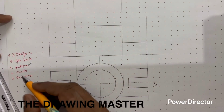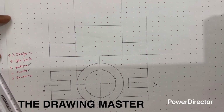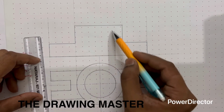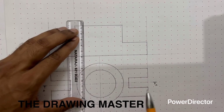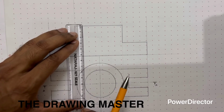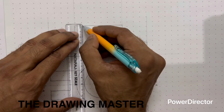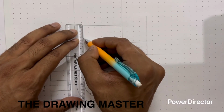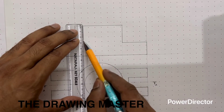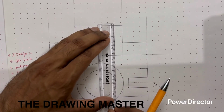Now after making the outline, second we have to draw the cavity. We have to find out the cavity. So in this whole section at the center, here is the cavity, means this circular hole. So let's take the projection from the circular hole. And this cavity means this hole is of depth 24. You can see this projection. This is aligned with this hole. Now here also we will take 24 mm depth.